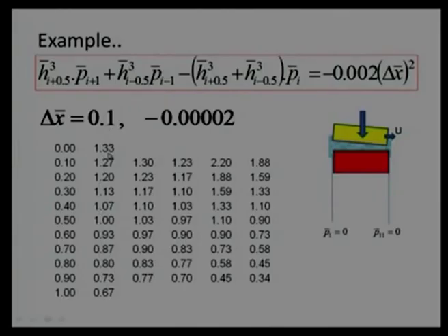The film thickness at that node, that means when we substitute the value of x bar, what we get is something like 1.33. Again, this is a non-dimensional number. This film thickness will continuously decrease because of the convergence. There is a taper angle, or there is a taper surface, or there is an inclination. That is why this film thickness will be maximum at the entrance and minimum at the exit, which is shown in this case.